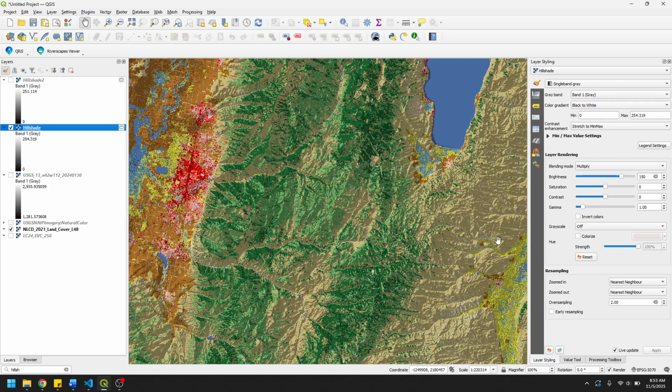All right, so that's the basics of how to do this. It's that simple. You can easily make these topographic maps or give topographic context to your layers using QGIS and a simple DEM that you can get from most places in the world. And if you don't want to use the USGS 3-depth data, there is SRTM data that's available worldwide that you can use for this.